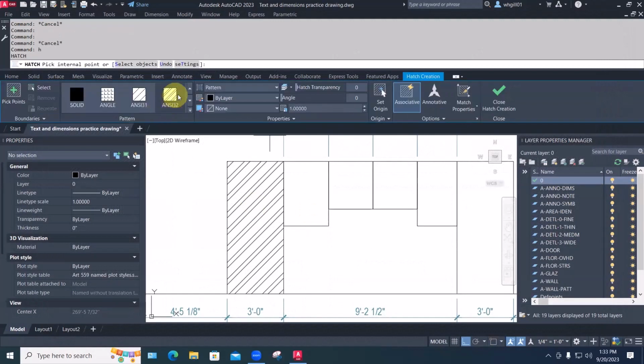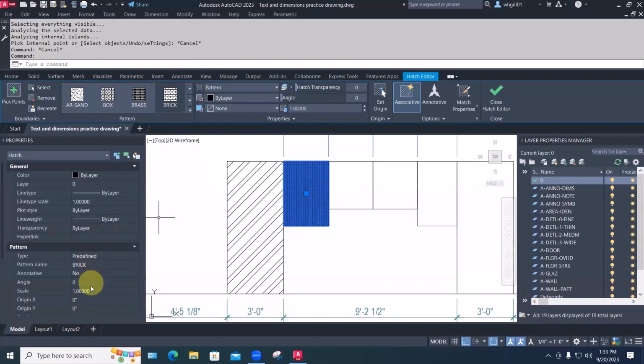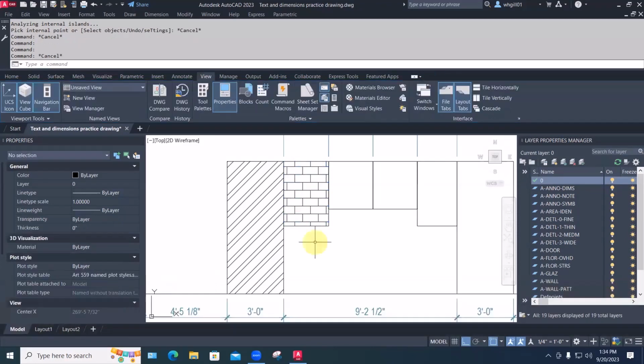Other kinds are more figured. Let's get rid of these. This is American National Standards Institute, and these are the ways it suggests that materials be represented. And there are other ones. Let's go down to the brick one, where we'll give it some sort of scale, where it starts to look like either brick or cinder block in an elevation. There's something like a representation of that thing.